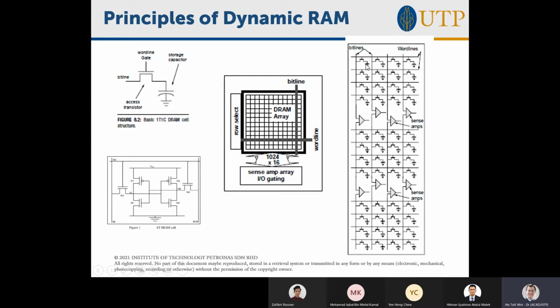The charge that is stored in each capacitor is actually really small, and there's a reason why we store a small amount of charge. A small amount of charge is easy to move, so your DRAM can respond very fast. If your DRAM stored a very large amount of charge, either the capacitance is very big or the voltage is very high, it takes longer to read it out because you have to transfer more charge, source more current, and it takes more energy. So it's a speed and energy argument. We like to keep the amount of charge and the voltage stored by the charge small.